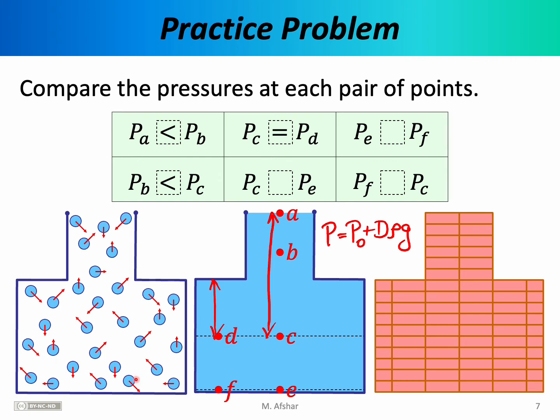In fluids, the molecules are free to move. They're essentially randomly located, and they are moving essentially in every direction. What that means is that a molecule that is located here 1 second could very easily end up over here the next second. And it can carry its energy with it, and when it collides with a molecule there, it will transfer some of that energy. That collision could result in a force that points in the x direction or in the y direction, or really in any direction, depending on the velocities of these molecules.